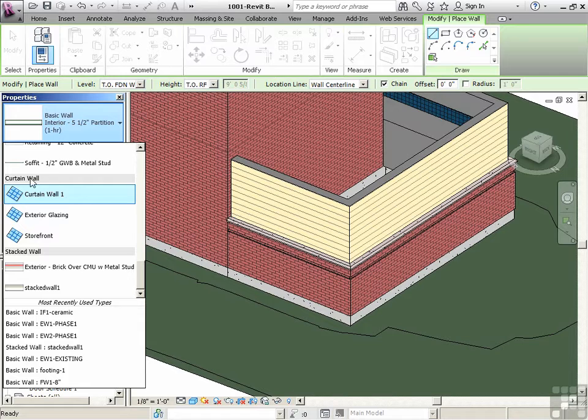And curtain wall is a little bit of a misnomer. Revit, when they named it, I would have preferred if they called it maybe a pattern-based wall or something like that. It's not necessarily a curtain wall, like an exterior glazing that's not connected to the slab. It's more of just a patterned wall, and it could be a curtain wall, it could be a window wall, it could be poured concrete, it could be tilt-up concrete, it could be fabric panels, wood panels.